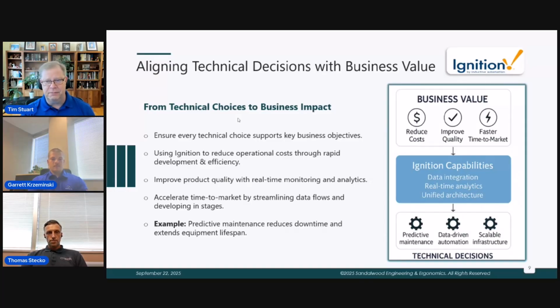So something like predictive maintenance, you have to build up enough data over time that that data store has predictive value. But while you're doing that, you can start to look at condition-based maintenance, where you just set up a tolerance and you say, hey, if this variable goes outside of this tolerance, then I need to look at what's happening with the machine. And you can set that automatically. You can set that using some math, if it's outside of 2 standard deviations or something like that. But there are things that you can do in the meantime while you're building up enough data to do the predictive maintenance to still get that quick win, to still get that value from the solution that you're putting in place. Yeah, for sure.